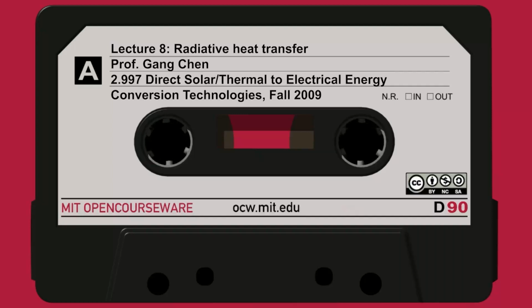So sigma T^4, and there is no area difference anymore. Sigma Ts^4 power minus this radiation, because now the absorber will radiate back, so minus sigma T^4. So that's the heat transfer from the sun to this absorber. Okay, that's the maximum you can get.